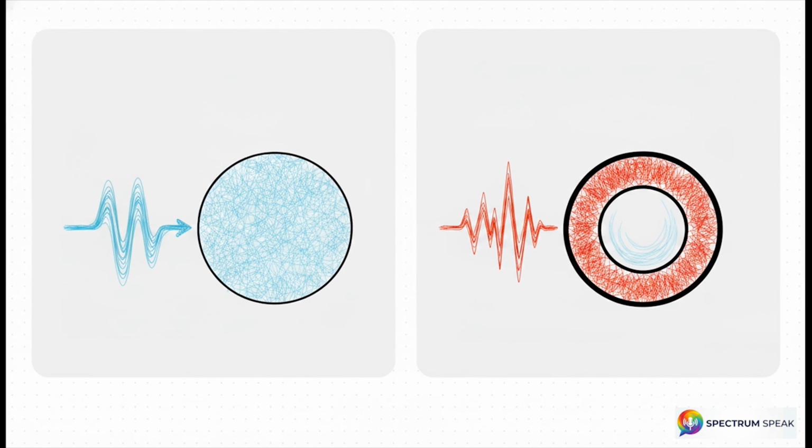Now, what's genuinely fascinating here is how a shield's behavior physically transforms depending on the frequency of the interference. At low frequencies, the transfer impedance is literally just equal to the DC resistance, the direct current resistance of the shield. But hit those high frequencies, typically anything above 1 MHz for your standard cables, and a phenomenon called the skin effect takes over. It's almost like magic. The skin effect forces the noise current to remain completely on the outside surface of the shield, while your signal current stays safely tucked away on the inside surface. It effectively separates those two currents entirely, eliminating any common impedance coupling.